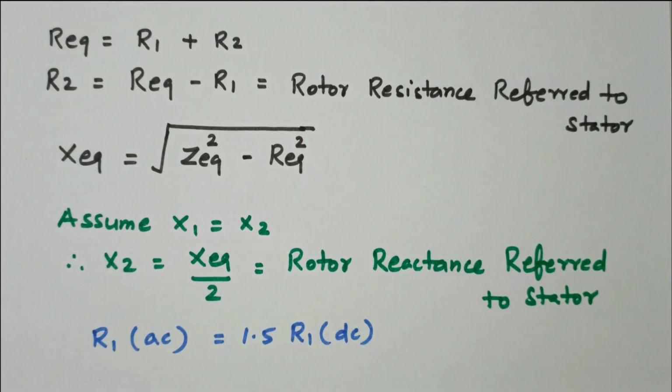Finally, we calculated the X0 value. In the blocked rotor test, the rotor is completely blocked, speed is 0, so slip equal to 1. We are able to measure short circuit current, short circuit voltage and short circuit power. Then finally we calculated R2 value and X2 value. By using these parameters, we are able to draw the equivalent circuit of a single phase induction motor.